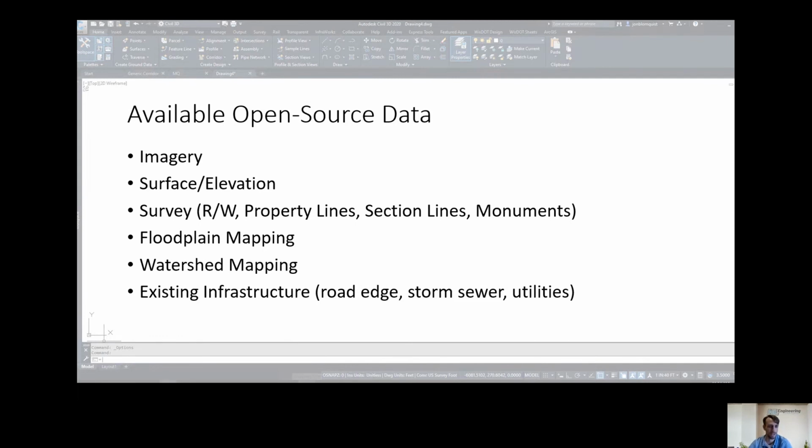Also available, which we won't really go into today but I'll discuss briefly here, are LAS files or DEM files that come in different file extensions. For those types of files you'll either need to use InfraWorks or something to get a usable surface out of them, or you could work with someone in your office who has an understanding of GIS and access to Esri GIS software to get some of these files into more usable data for a Civil 3D user.